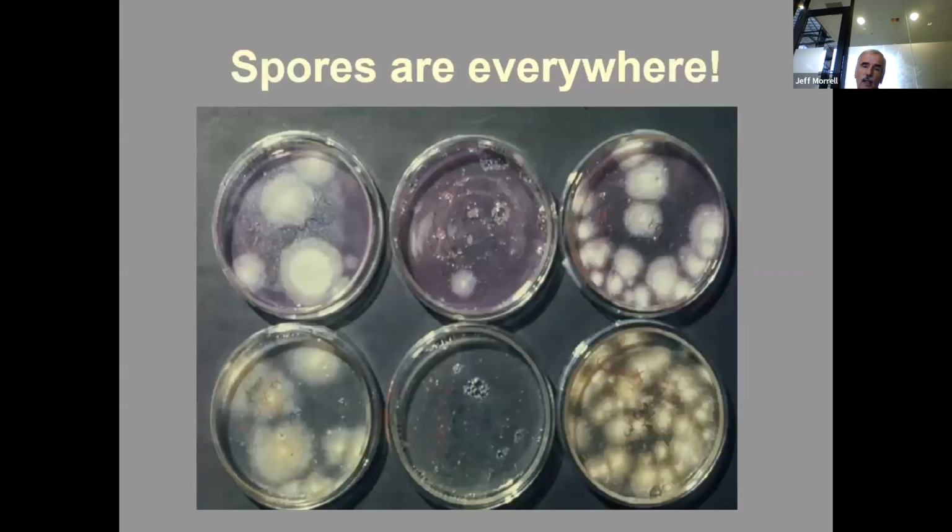It's important to understand that wherever you are, there are fungi. Even in Antarctica, there are fungi slowly growing on a lot of the timbers, say at the Mawson huts there. These Petri plates show that they were open to the air for a short period of time. They've got a nutrient media on them, and spores landed and started to grow. So what you see as the white spots are fungi that were just hanging around in the air. We breathe them in every day. So it's important to understand that if you create conditions that are conducive to fungal growth, something will eventually get there. And that's why design and protection become so important in using timber.